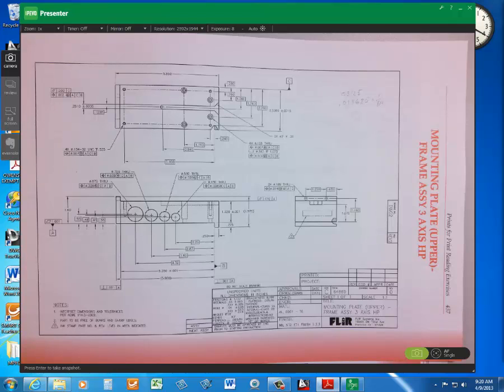Okay, a pilot hole, 7/1000 in position, 7/1000. 2.5 hairs, roughly. It's pretty tight control. Now, you look at the counterbore, well, they made it 14/1000.